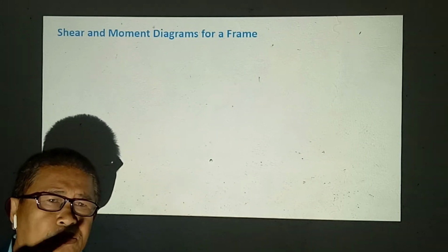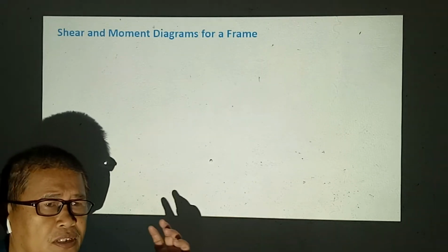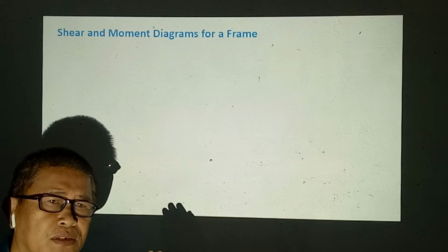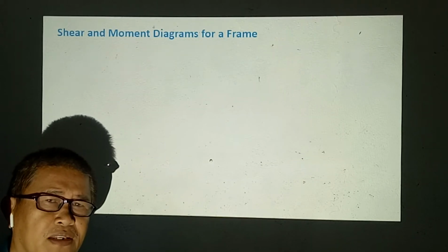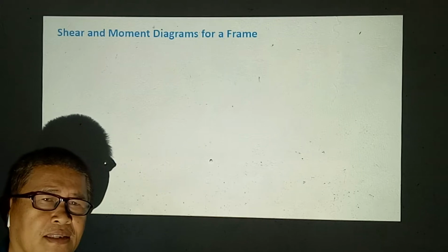So our reinforcement should be placed at the tension side. So a moment diagram drawn positive at the tension side simply gives the designer where the location of the tension bars should be placed.